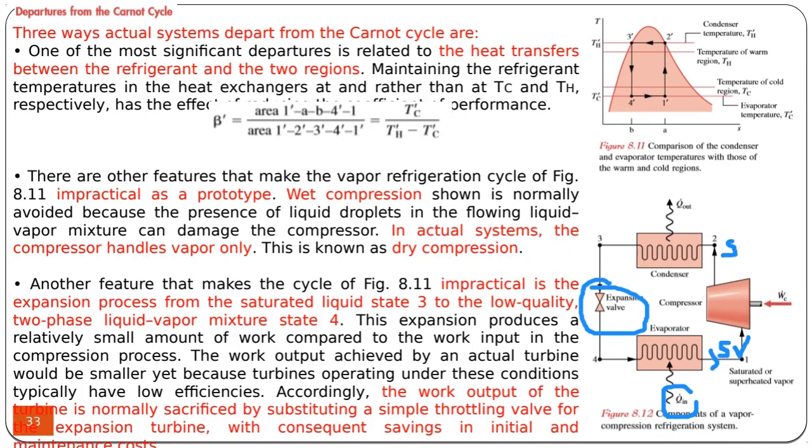So at the inlet of the condenser, we have superheated vapor, which is cooled down to saturated liquid. Then saturated liquid passes through the expansion valve to a lower pressure, and as its pressure decreases, it expands into a vapor phase or a mixture phase by absorbing heat from the surrounding.